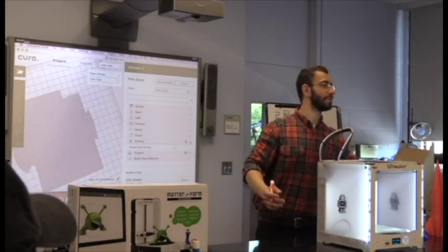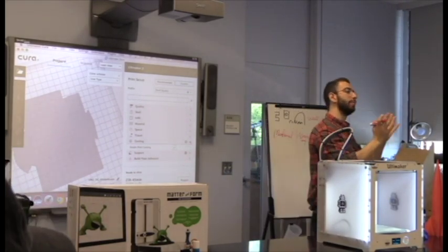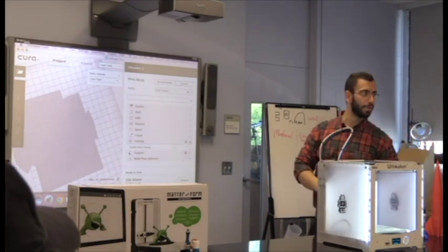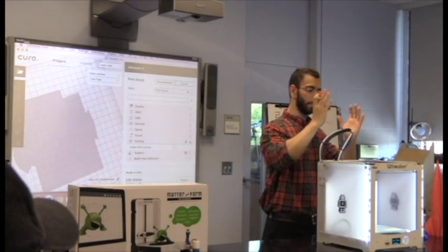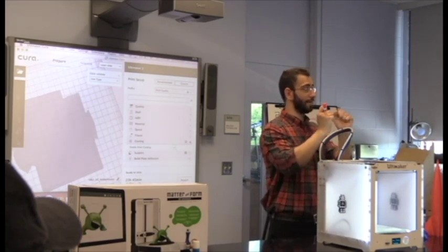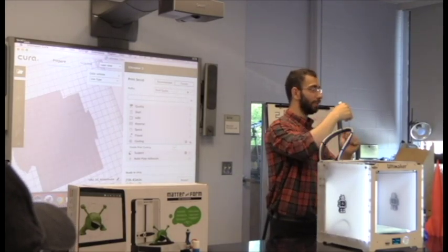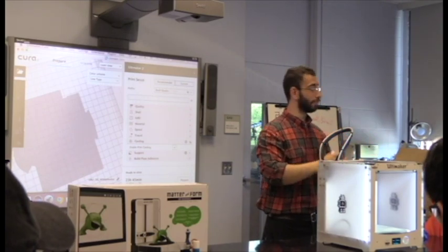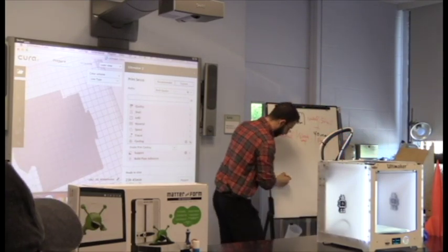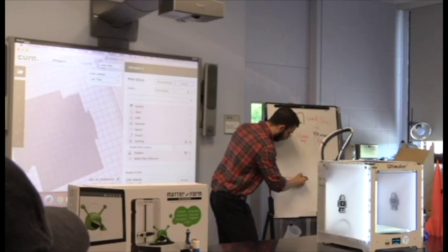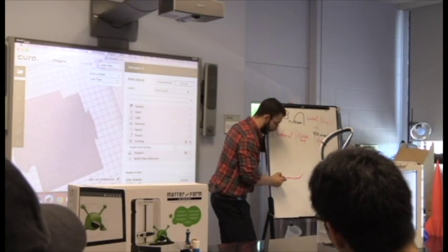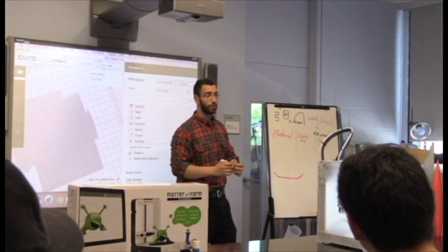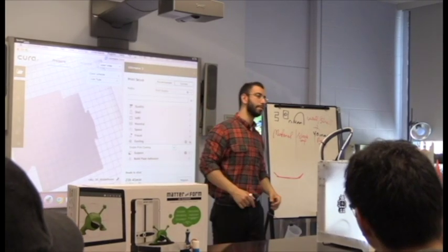Why is that important? Well, imagine if you have something very hot, and the moment there's something cold, it's going to solidify right away. You don't want that because when stuff solidifies, remember, plastic tends to shrink. So as you build up layers, it might warp your print. So instead of looking flat at the end of a print, it'll kind of warp upwards on one edge, maybe on both edges. The whole thing could warp up. Okay, so that's why for certain stuff we need the bed to also heat up.